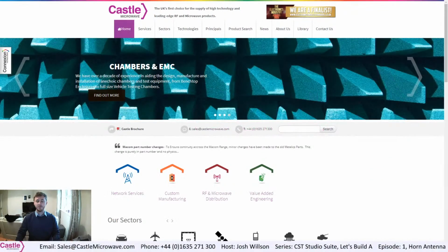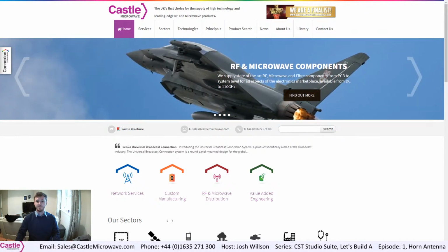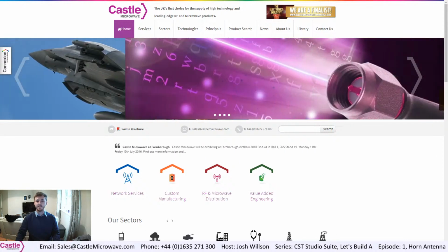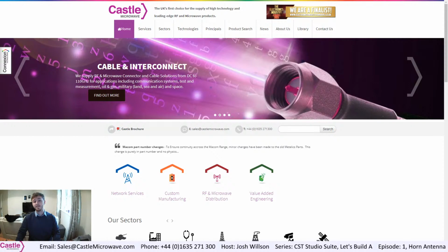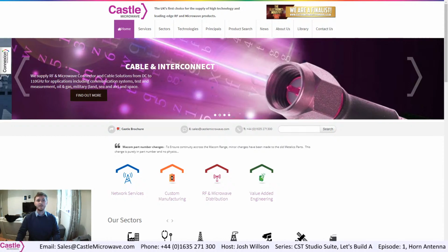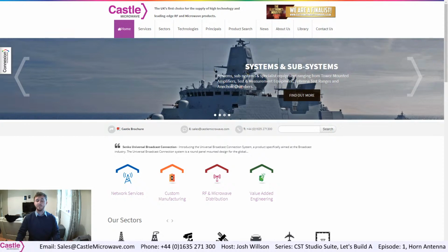Today, we will be constructing a horn antenna and studying its gain performance. Horns are widely used as antennas at UHF and microwave frequencies. They are used as feed antennas for larger antenna structures such as reflector antennas, and as standard calibration antennas to measure the gain of other antennas. They offer moderate directivity, low VSWR, broad bandwidth, and simple construction and adjustment.